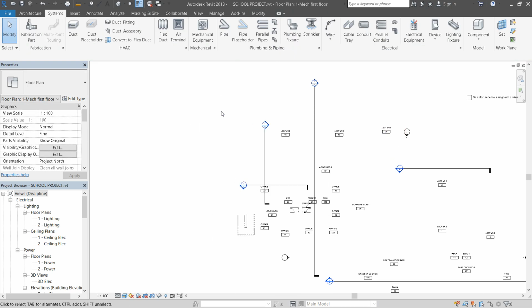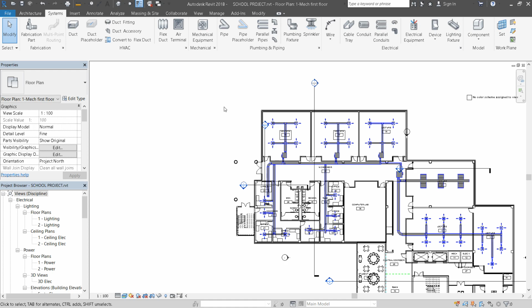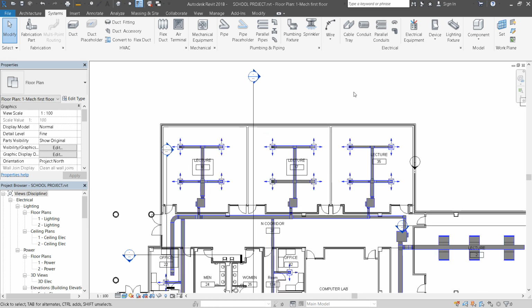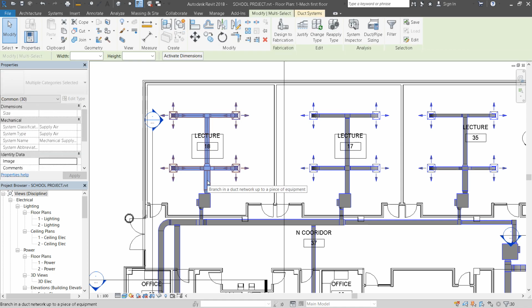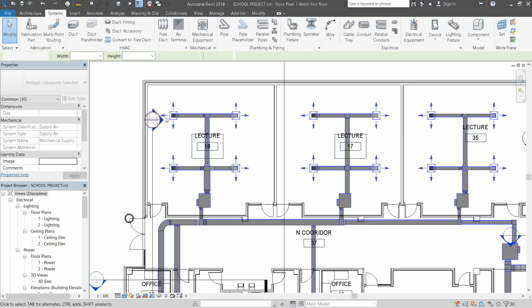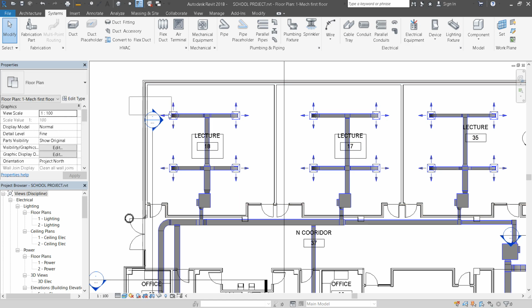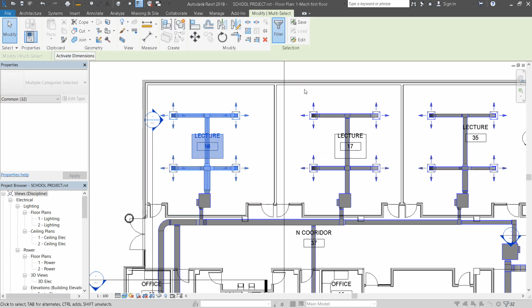This is one of the things regarding the duct. It's a very good thing. Now if you want to assign insulation, because there are heating and cooling systems, you are supposed to assign your insulations over there. The same method. Select your system first of all. Click that over there. There is no heating over there. Let's remove first. Let's add terminal not in the selection list. Filter.